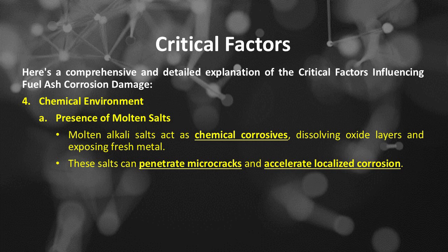Number A. Presence of molten salts. Molten alkali salts act as chemical corrosives, dissolving oxide layers and exposing fresh metal. These salts can penetrate microcracks and accelerate localized corrosion.